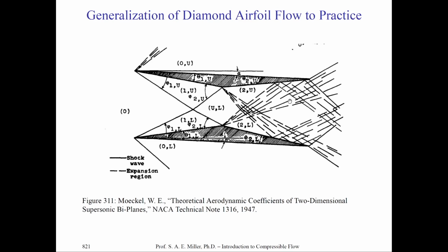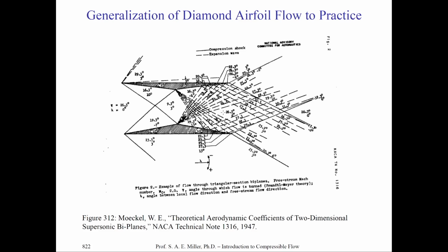And indeed, if we put fuel in the middle and burnt it, we would indeed have an engine with no moving parts that consists of a compressor from the shock waves and a nozzle from the expansion waves and heat and pressure addition from a combustion process with no moving parts. It's a genius idea and analogy. Let's look at more complicated examples.